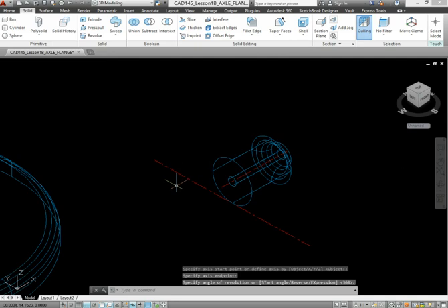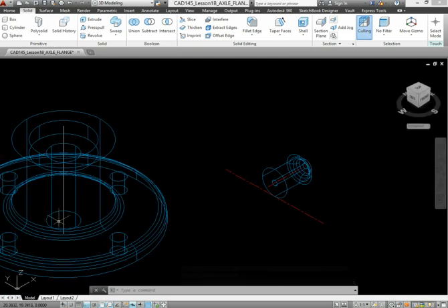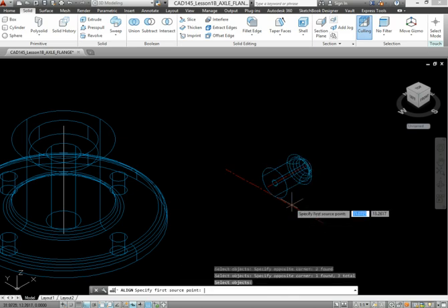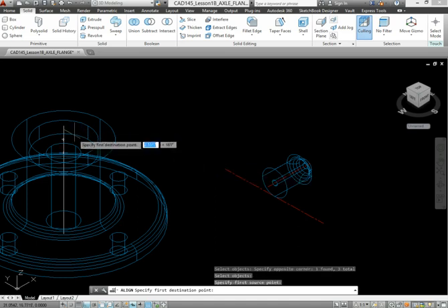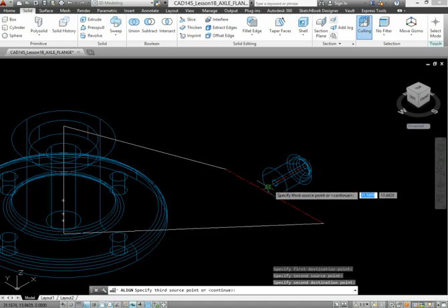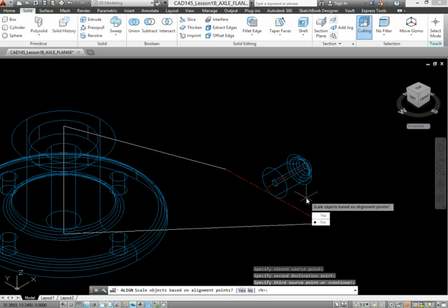and we're going to move this into place using the align command. I'm going to show you why it doesn't work, but then we'll do it the right way. But we're going to align it to here. This axis here is the same as this axis here from our previous step. Type in align, A-L-I-G-N. Select these objects and this center line. Click enter. Our alignment is going to be here to the top of this, here to the bottom of that axis, and there's nothing else I can move onto here, so I'm just going to hit enter. It's going to ask me, do I want to scale the objects? The answer is going to be no. You're going to see it move and rotate into place.